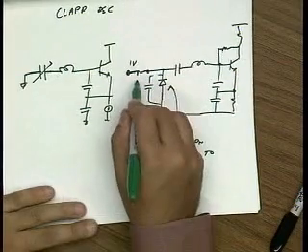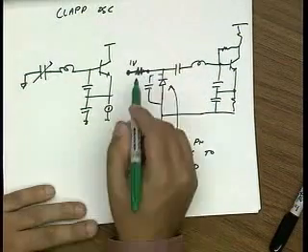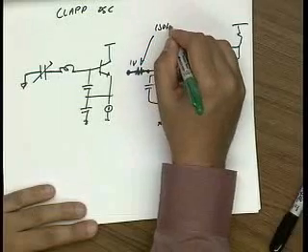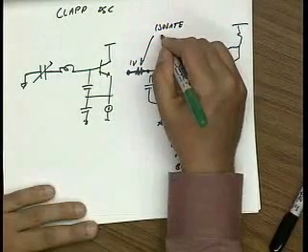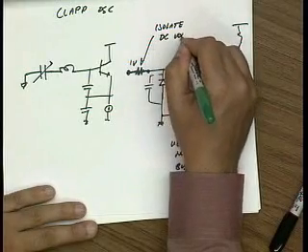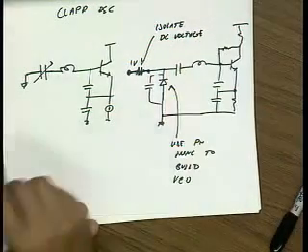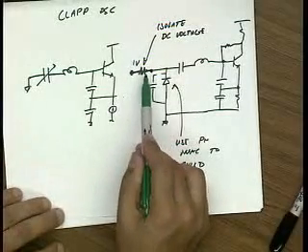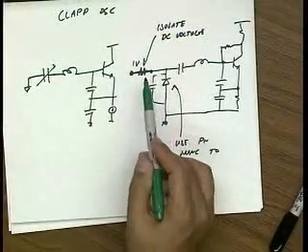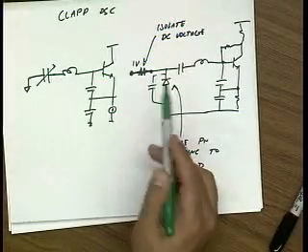I drew a bad resistor here, but this is a resistor. I need to isolate. Yeah, good point. Basically you want to isolate the DC voltage from the AC signal, and the way you do that is you use a pretty large resistor here. This might be a kilo ohm or something. You could also use a big inductor.